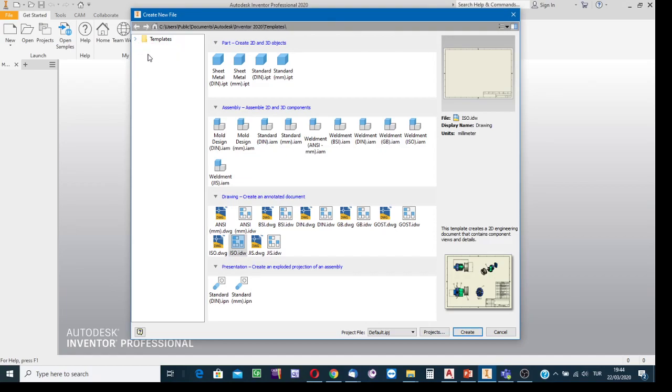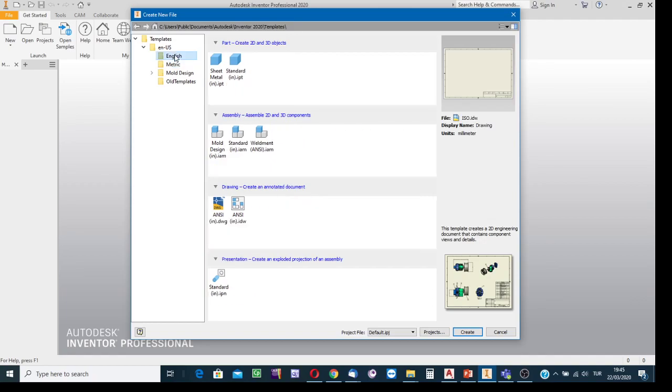If you find it in this compact form, then click on the listing arrow in the first pane of the dialog box, and then click on the other arrow, and then find the Metric English options. If you're going to create the views as first quadrant views, make the selection on the Metric option. If you're going to create the views considering the body as located in the third quadrant of the universe, then select the English option.